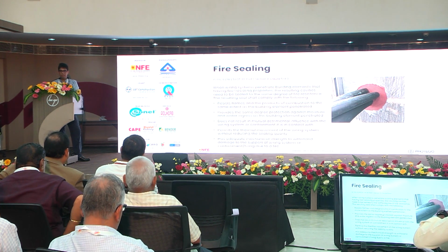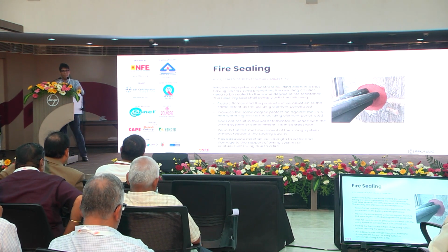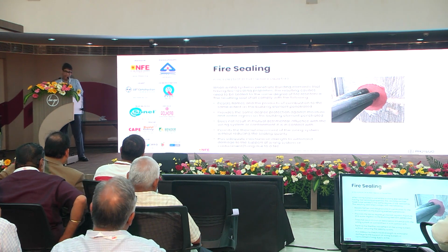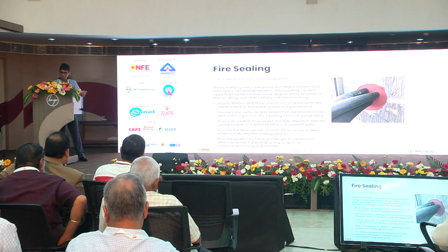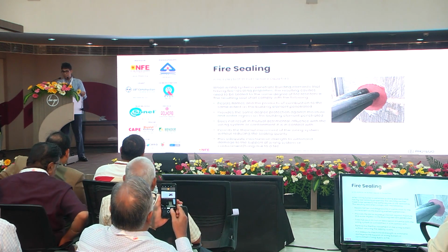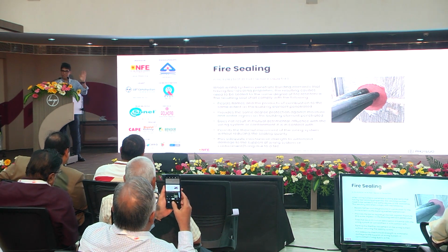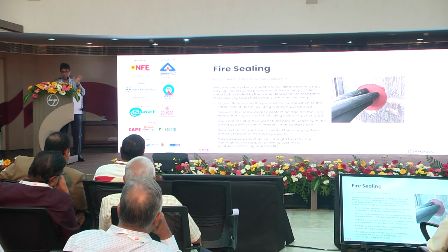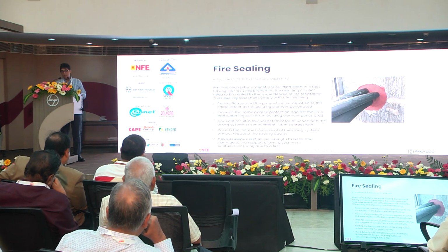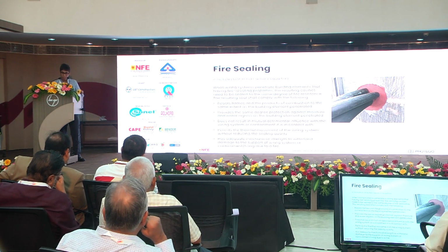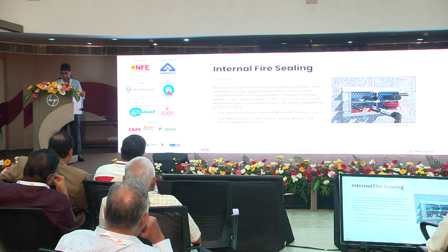See, basically, how do you ensure a proper seal? I've tried it myself, okay? I've bought a fire sealant from Fischer, and I've tried making a fire seal with a silicone gun. I have experience using silicone in bathrooms for water sealing, but I was unable to make a proper fire seal. And even if the seal is proper, the product has to be selected because, A, it has to resist the flame and the products of combustion to the same degree as the building element. It needs to have the same rating for the ingress of water and moisture. And like Mr. GK said yesterday, it should not have a detrimental impact on the cable. Otherwise, you're going to have a degradation in insulation.